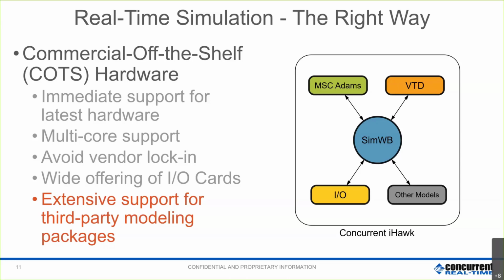You want to integrate this in the bigger simulation. What do you do? You make a user model, you bring this C++ code into Simulation Workbench, and again, through the magic of RTDB, the real-time database, you can make the Adams model talk to your own C code without doing anything by yourself. It is all simple RTDB communication.